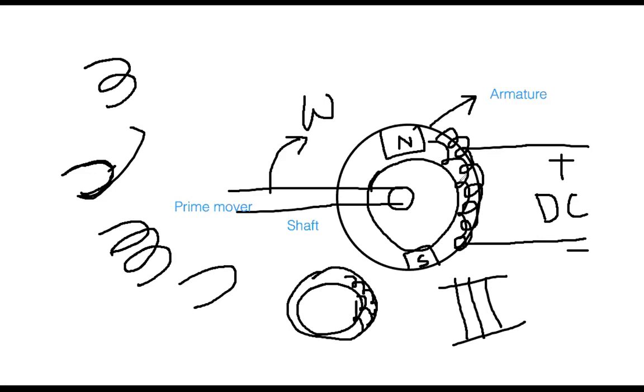The thing is that from time to time these coils get damaged. So if you have only one set of coil and that is gone, then you are not getting anything. That's why there is an alternative arrangement, the parallel path. For example, if there are 3 sets and one set is gone, you still have the 2 more sets. If this is gone, another set is still present. And they are placed in parallel because in the case of parallel, the voltage remains the same. Yes, you got it.